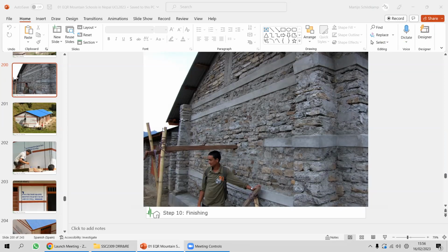Yeah, and maybe may I add something here? The whole purpose of confined masonry, confining the masonry panels, is to increase the integrity of the panels so that it works as a single wall panel, as a complete thing. The purpose is not to provide flexibility in the frames, because those are unlike reinforced concrete.